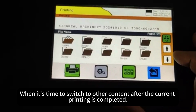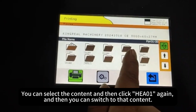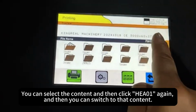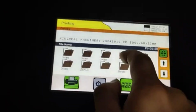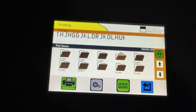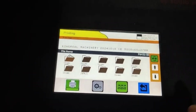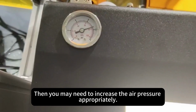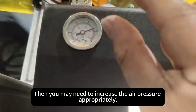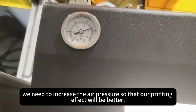When it's time to switch to other content after the current printing is completed, you can select the content and then click HEA01 again, and then you can switch to that content. Look, the switch has been completed. Finally, you need to pay attention to the air pressure of the machine. If you find that there is a little residue in the printed content, then you may need to increase the air pressure appropriately. When we print at a high speed, we need to increase the air pressure so that our printing effect will be better.